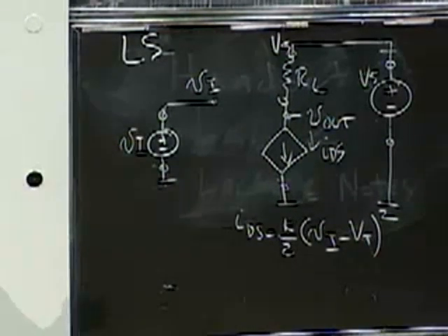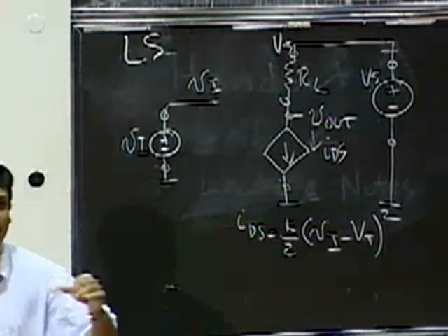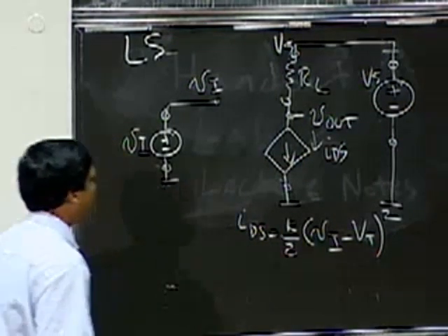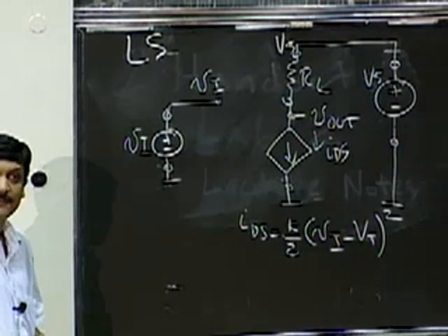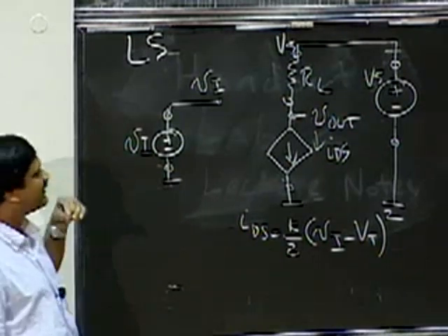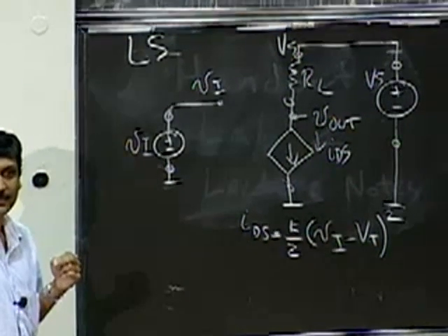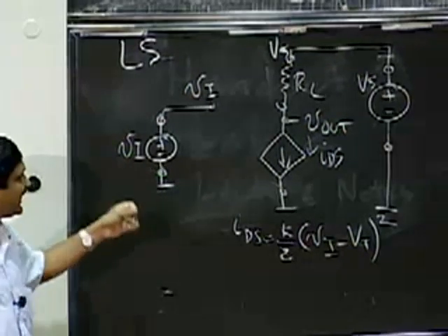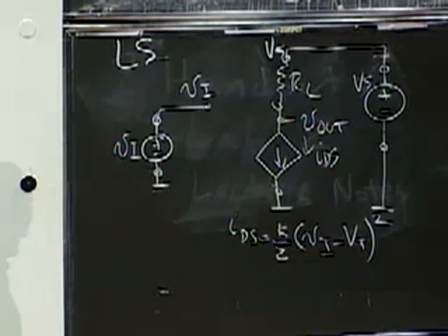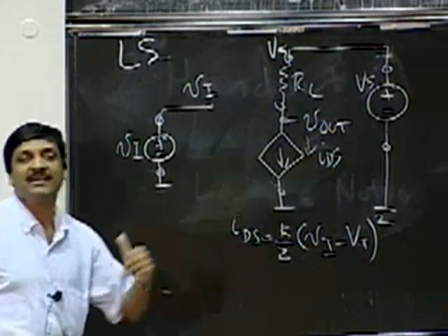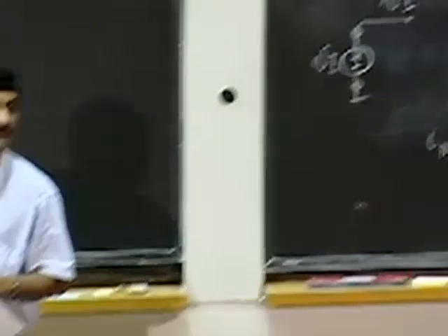And then once I have a linear circuit, I should be able to analyze that linear circuit using methods 1, 2, and 3, superposition, Thevenin, node method, and so on. And certainly the intuitive methods like superposition and Thevenin make life a lot easier for me with linear models, and thereby get the function that I'm looking for very quickly. Okay, so again, my claim is that I can replace each of these large signal models by just small signal equivalents, and then just analyze the resultant circuit. Okay, and I claim that I should be able to get the same answer.